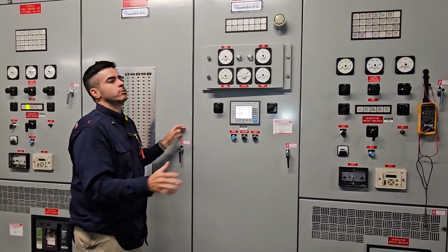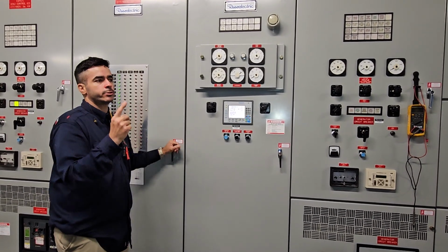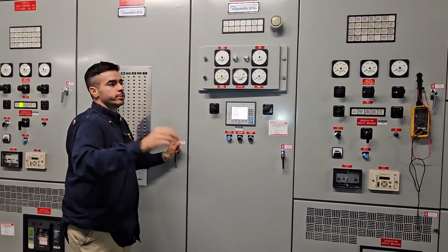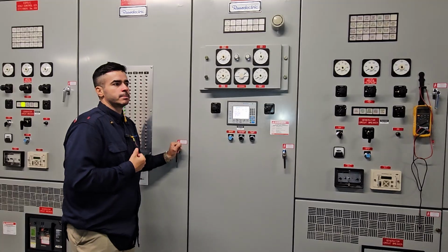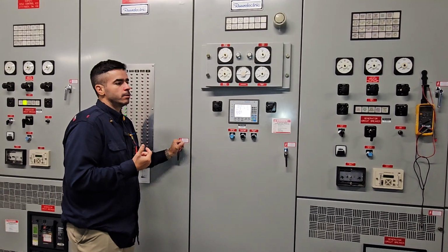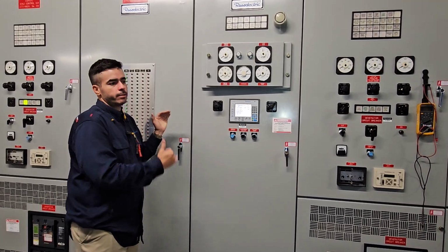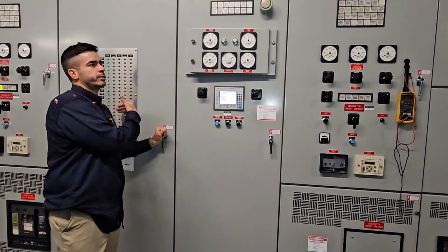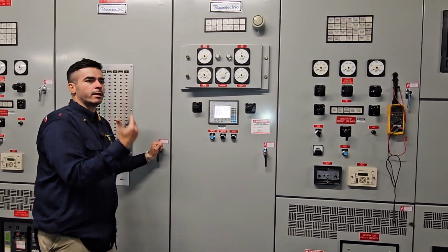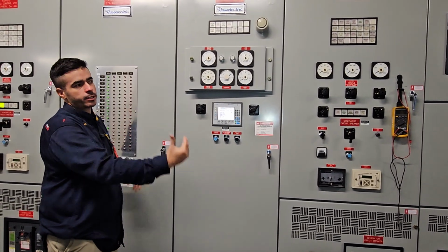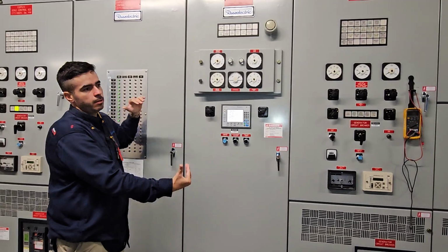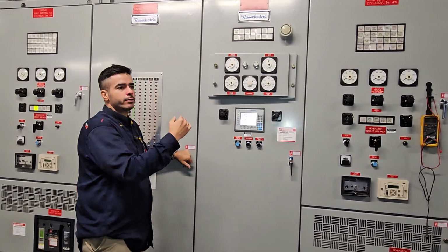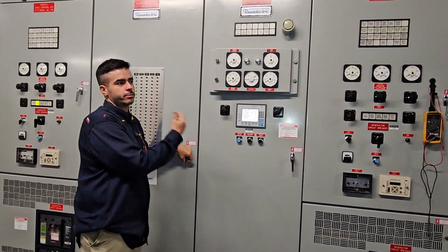When you lose power, there is no closed transition operation because there is only one source to go to, right? So it will call for the generator to start, and as soon as it sees emergency power, boom, boom, it opens and closes, right? So when it's taking too long, it's because we have both sources available, and the ATS has to make sure they are in sync. Same thing when you are retransferring to normal after an outage. You already have both sources. You are still connected to the generator, but you already have normal, and it's just timing down. So the timer gets to 0, and now it's ready to go, and then it takes another 5 minutes to transfer back.